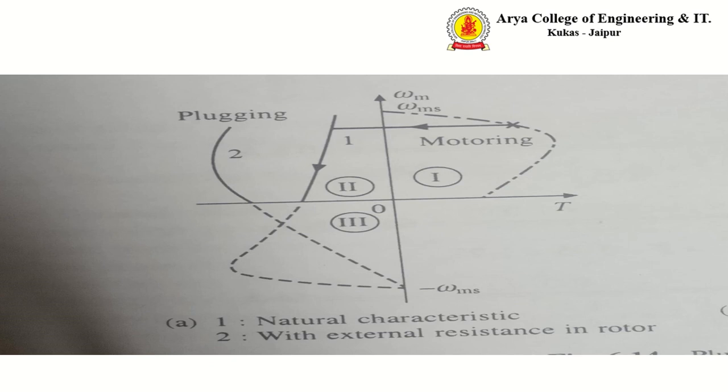This operation is braking, and this type of braking is reverse voltage braking because it depends on the reversal of voltage by changing the supply terminals. This operation is from the third quadrant to the second quadrant.